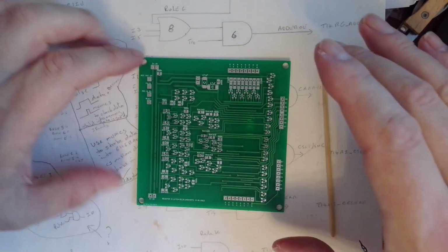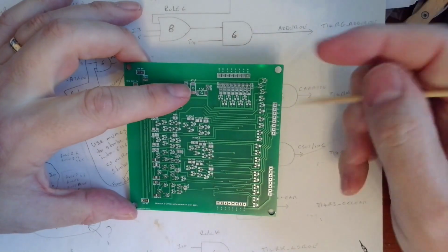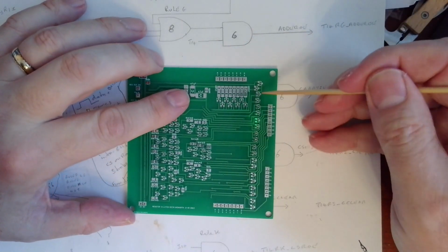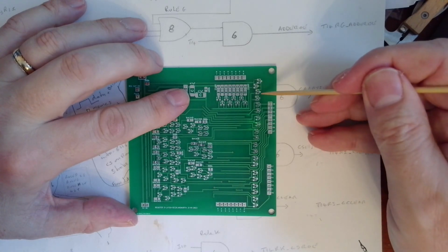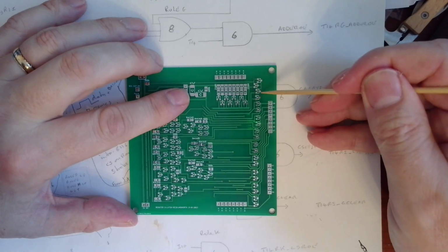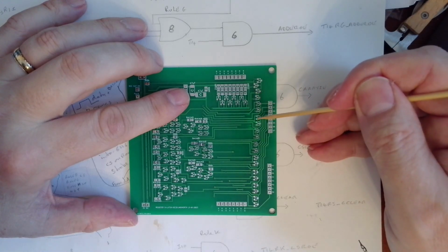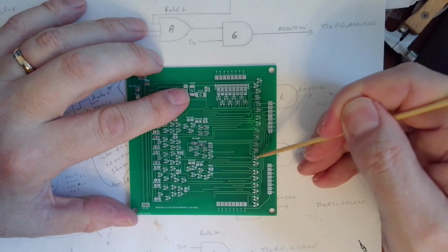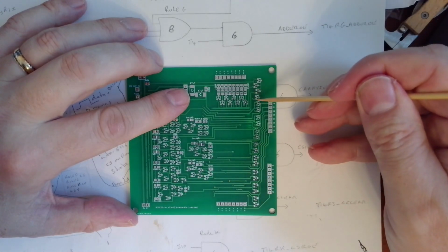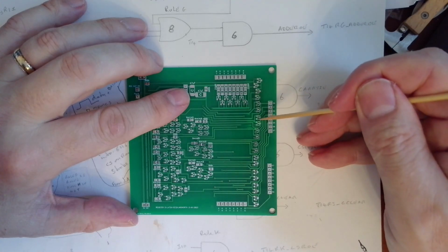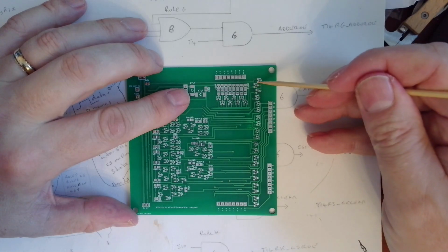Here we have the original register circuit board. So up here we have the 2 transistors for the inverter for the control signal. Here we have the 2 power transistors for switching the power. And that's bit 1, bit 2, bit 3, bit 4, 5, 6, 7 and 8. So these are the supply to all of these outputs controlled by this signal here.